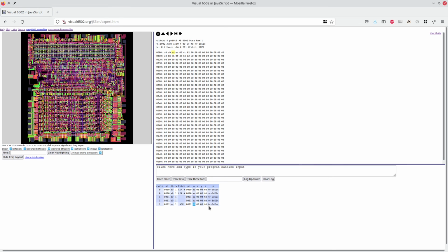You will also notice that the negative flag is high, because D9 has bit 7 set, and the 0 flag is low because D9 is not 0. So, first cycle of the NOP instruction, and we're from address bus 002, and the program counter is 002. Second cycle of the NOP instruction, and we see that the program counter increased to 3, because after all, we finished reading the opcode and don't need it anymore. And the address bus says 3, and of course, the data bus says EA because the next instruction over is also no operation. But the next instruction is again a fetch of a new opcode, but the program counter remains the same. And this is because we did not advance the program counter. We did not consume this value. We did not use it yet.